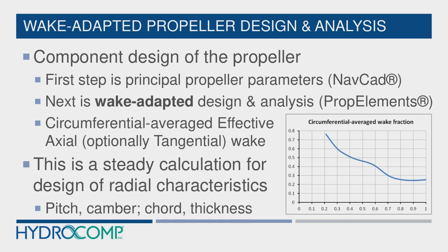So the next step is this wake adapted design, and we would use a tool like Prop Elements for that, where it's a steady calculation based on the circumferentially averaged effective axial wake. Optionally, we can also include tangential wake at that point.